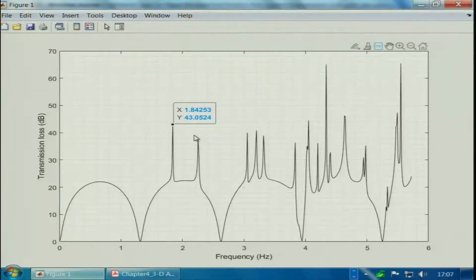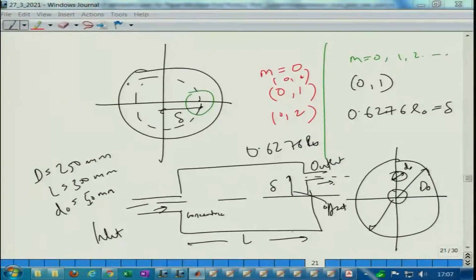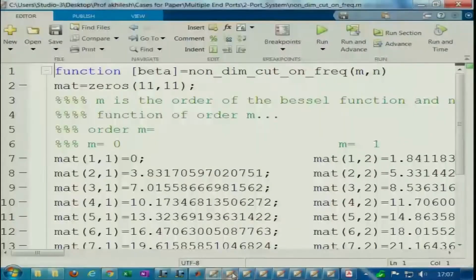The azimuthal modes are there if one of the ports is centered and the other port is at an offset; that is why you are getting a peak, otherwise this would have failed right here. You are getting another peak at this point, these are the cross modes, at k naught r naught of 3.05, and this is a peak because of the radial offset.